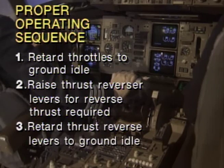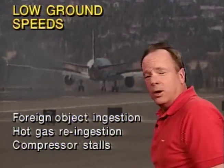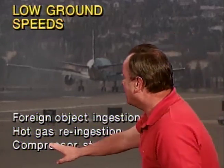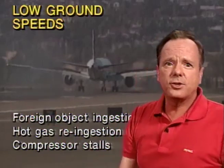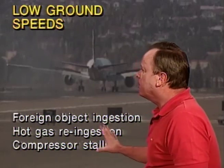Now, you can, in some cases, actually use reverse thrust to back the airplane up on the ground. It is not considered to be a good idea. It is something to be done with great caution, because operating thrust reversers at low ground speeds can make you pick up sand and other foreign objects, so you can get foreign object ingestion. Also the hot gases can come back into the engine, so you have hot gas re-ingestion. That's considered to be a bad thing. And also the air from the exhaust gets up to the front of the engine and confuses the air at the front of the engine. That can cause compressor stall. So using reverse thrust on the ground is something to be done only with great caution.